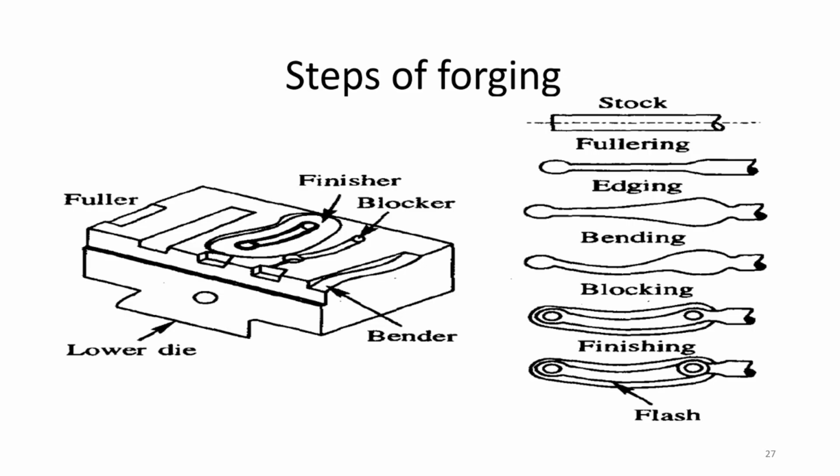So the pattern allowance will be more, so the order can be placed by putting brass in front of steel for pattern allowance. Which allowance? The allowance that we give for the pattern for solid shrinkage. Your pattern will be made bigger in case of brass, because you need to provide extra allowance, since your brass will be shrinking more.